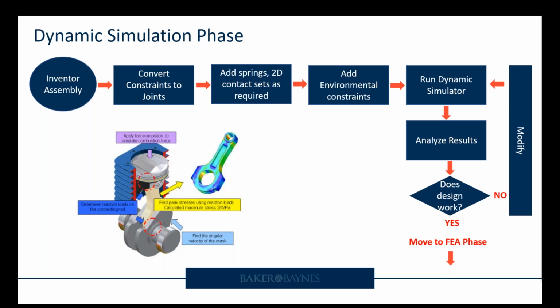Now, Autodesk Inventor Simulation Suite software combines a simulator for motion dynamics with a powerful linear finite element stress analysis application. To understand the performance of a proposed design, a designer starts by running the dynamic simulation tool to calculate the dynamic performance. The results of the simulation represent the positions, velocities, and accelerations of the mechanism throughout its operational cycle.